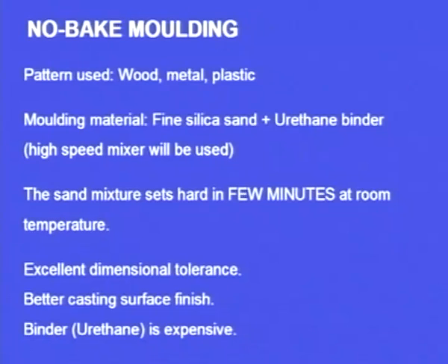Baking means we will put it in an oven. So, people were calling it the baking moulding system, but that was causing some problems, that was taking a lot of time. Later people developed the carbon dioxide hardened sodium silicate moulding process, but that was expensive. Later people developed this no bake moulding, in which we are not going to bake the mold, we are not going to place the mold in any oven.